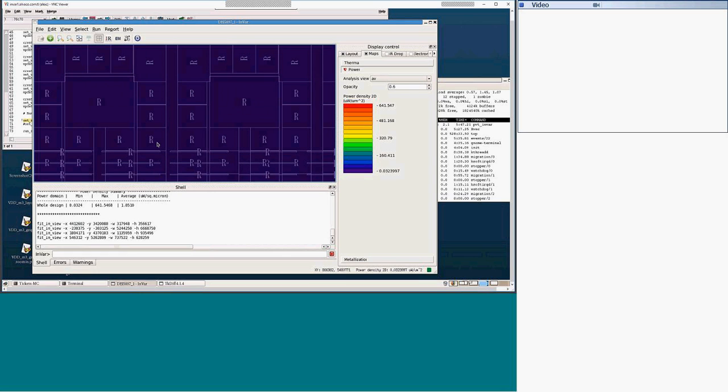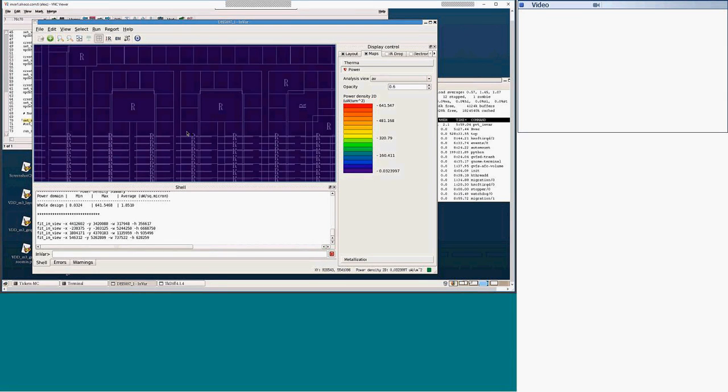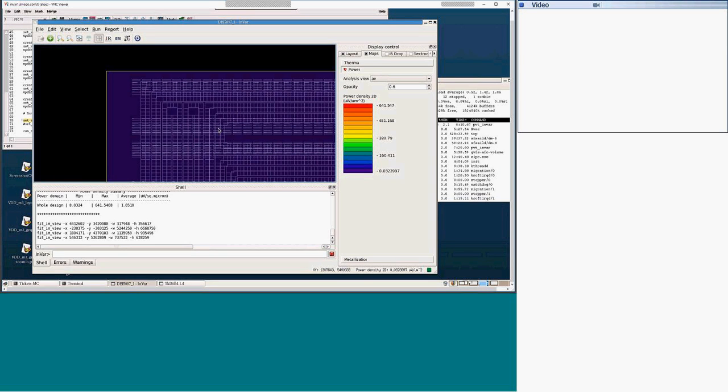If we zoom in, these are all R devices. That's probably what counts: such a big actual layout has just one piece of metal resistor, but for the simulation, we cut the resistor, each piece, so you see the temperature in the certain area you'd like to see the temperature. So we divided the resistor into small pieces.